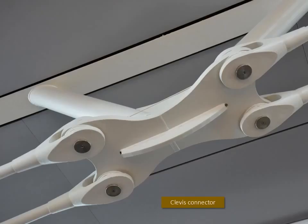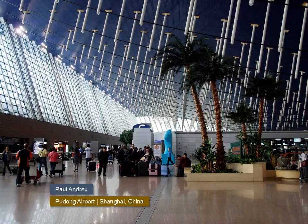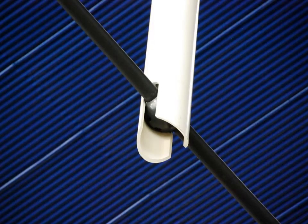The most normal way to connect tension rods to plates is through the use of a clevis. These make simple rotating pin connections. The bottom chord of the innovative trusses in the Pudong Airport use rods, as these elements are always acting in tension. The attachment between the rod and the hollow structural steel compression member is achieved with this innovative steel ball connection.